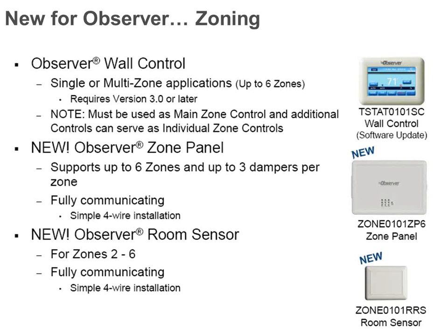They're thermistor sensors, so they basically get a voltage passed through them, and based on the resistance, the voltage drop based on temperature, you would be able to see that temperature reading. The new ones, in the bottom right-hand corner of the screen with that zone part number, are 4-wire communicating sensors. They're kind of like the Observer control, except there are no LCDs that display on them. And we'll talk about where you can use those in a second.